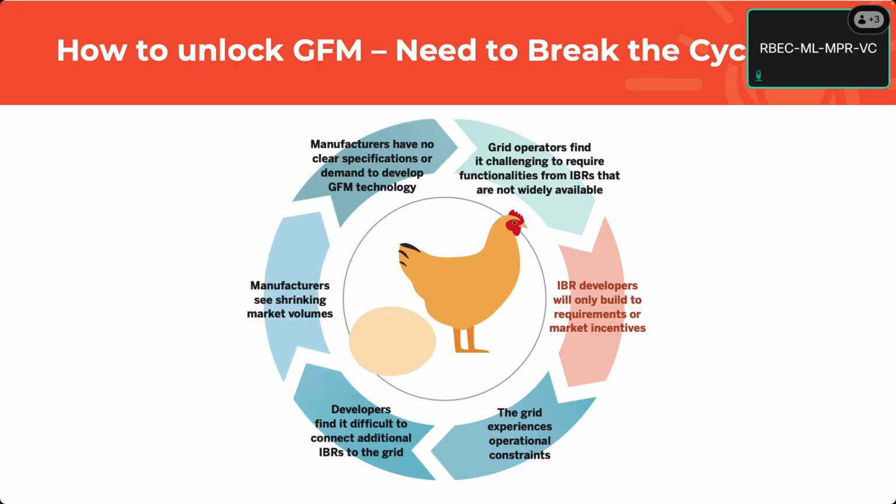You're adding a ton of damping at subsynchronous frequencies, so you're basically solving your SSCI problems without doing any control tuning or any work. And you're making your whole plant a little more stable. It would be nice if you got paid for it as well. Of course, you're going to ask for that. But why wouldn't you also just do it?